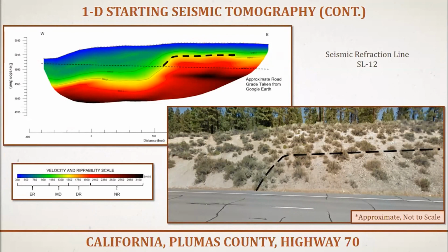Notice that the vertical distribution of velocity contours in the final model shows a relatively large spacing, indicating a more gradual velocity gradient. If the velocity structure is actually more abrupt, even though we use a smooth starting model, the velocity contours will still be expected to be spaced closer together and exhibit a higher velocity gradient. As anticipated from initial review of the travel time curves, we can see a distinct structural change at the center of the model.